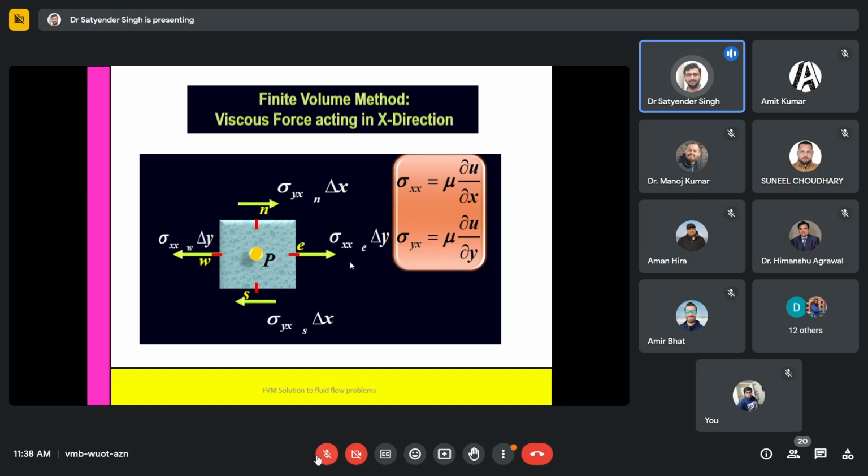For a fluid flow problem, that region is near the boundary or near a wall where the boundary layer forms. In the boundary layer we consider that momentum or energy transport occurs due to molecular motion, because of their random motion. There, the viscous forces also have a major, significant effect in the origination of the boundary layer.